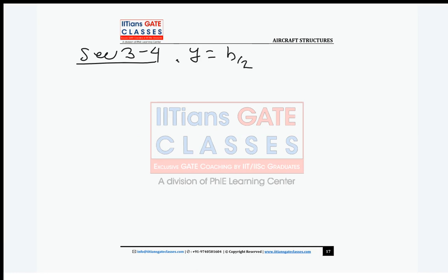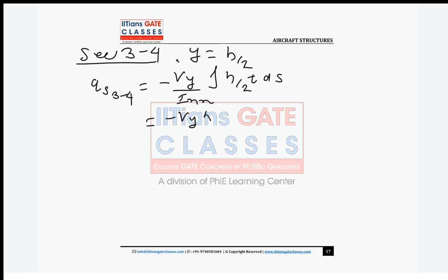Okay. So guys, now what will be your QS 3 to 4? It will be minus Vy upon Ixx integration h by 2 T ds. Again, you can take h by 2 T out and integrate. So what we get? Minus Vy h T upon 2Ixx, then integration ds means s plus constant q naught.